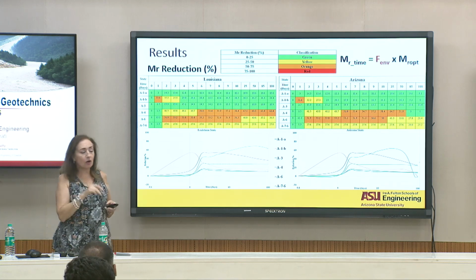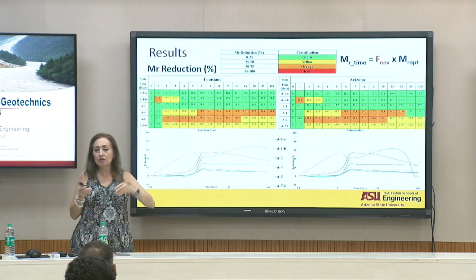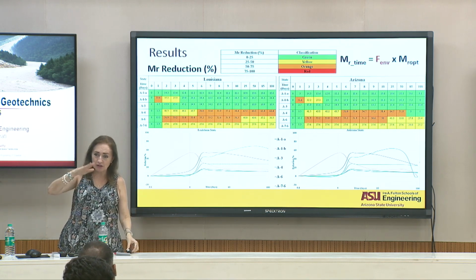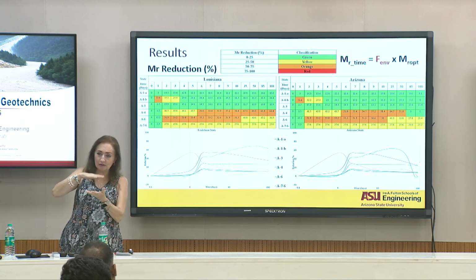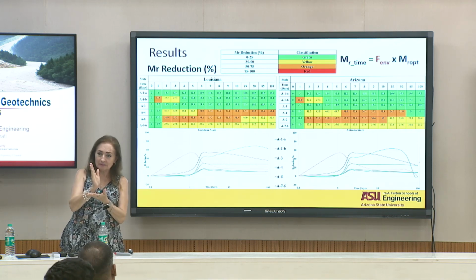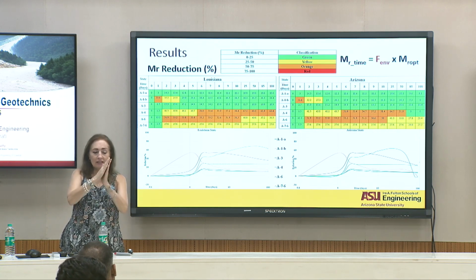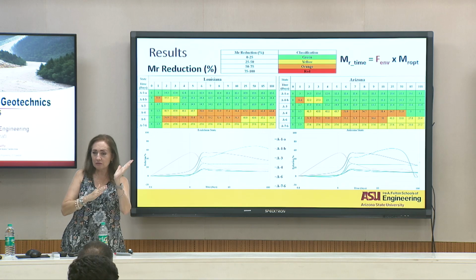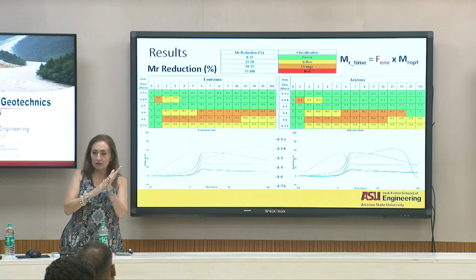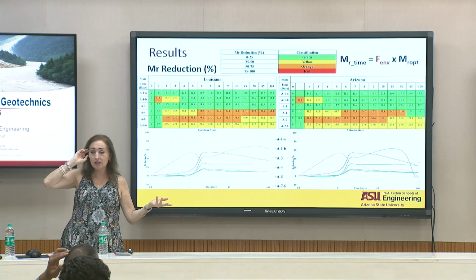So what you're saying is, no, but again, the resilient modulus of the soil is the capacity of the soil to withstand that number of repetitions, right? And this is the recovery strength that they get. Now, rutting is already when you do have failure, when you have a shear failure. You basically do a test with a deviatoric stress state until you fail the soil, and you count the number of repetitions that you need to fail that soil.